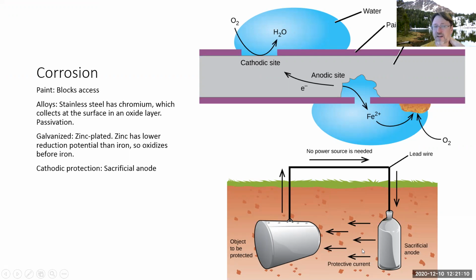so that when there's electrochemistry going on due to the presence of moisture, the presence of oxygen, anything of that sort, then the sacrificial anode starts to etch away before the object you're trying to protect does. Now, it's sacrificial in a very important sense. It is going to actually eat away. And so once this thing completely eats away, it will no longer be protected, and your object will end up starting to corrode at that point.